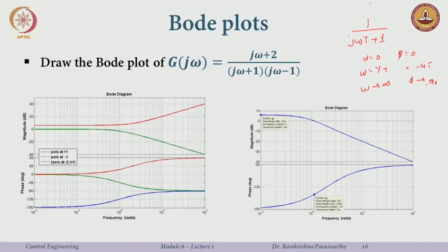So, what was the gain margin? Well, the closed loop system is stable; you could just look at 1 plus this thing being equal to 0. The closed loop system is stable, but it has a negative gain margin, minus 6. Which essentially means, if I draw the root locus, I have a pole here and a 0 here. This is plus 1, this is minus 1, this is minus 2, and this is 0 here.